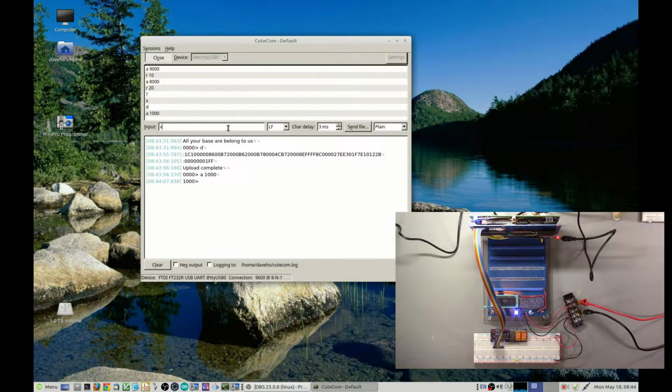And then if we do X, what we should see is that this is the count program that's going to display an increasing count on the hex display here, which is just outputting increasing binary values on port A of our 82C55A device. All right, let's see if that works. So we should see this count up, and it does. Okay, so that's quite promising. That does suggest that the system is still working. All right, let's try to connect the interrupt controller.